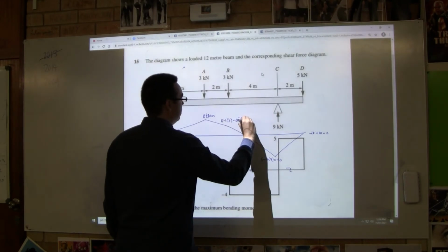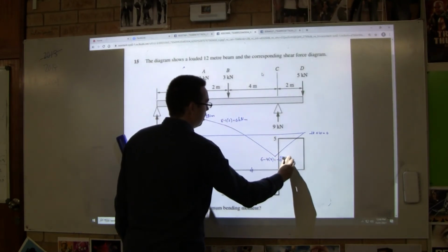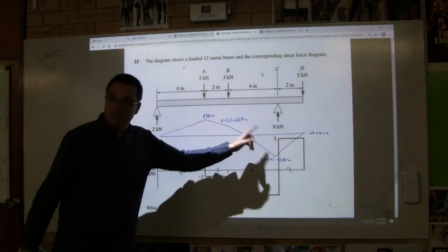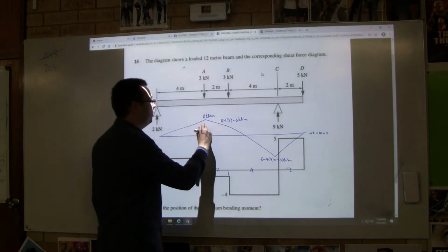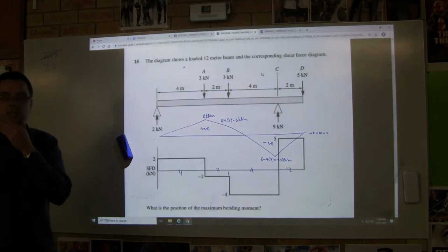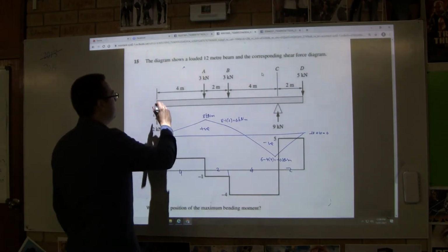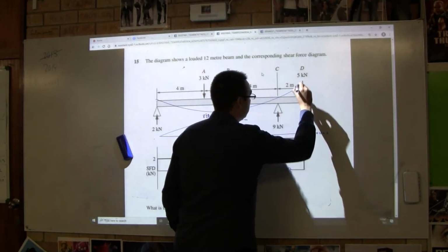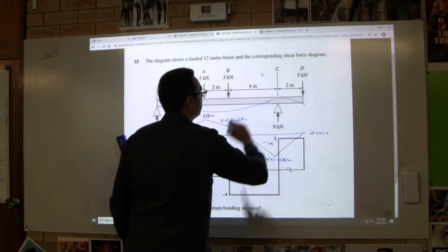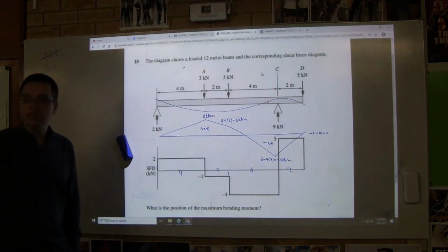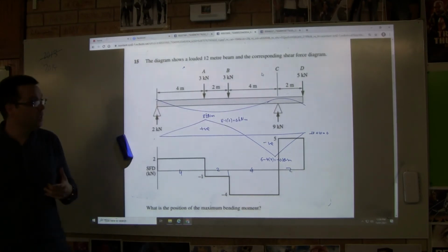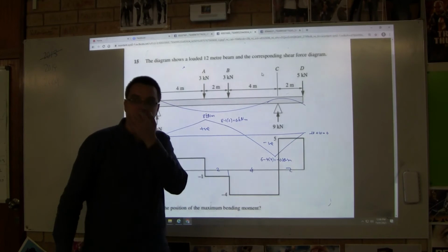Each of these is kilonewton meters. And what we can do is look at that diagram. If we have a shape like this, this is positive and this is negative. What that means, and it'll also give you an idea of how the thing's going to bend, is that it looks like the opposite of the shape. So it's actually going to go like this, like that. That's kind of how that thing's going to bend. Do you see how it's opposite to the shape? And wherever we have a cantilever, we're going to have something like this. We're going to have a negative area.